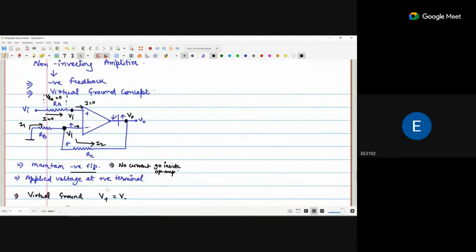we assume that we are always using the operational amplifier in negative feedback. And in negative feedback, we generally consider the virtual ground concept. This is the way to solve an operational amplifier. When you go till week 11, the only method is that you have to maintain negative feedback, and in the case of negative feedback, you always consider the virtual ground concept.